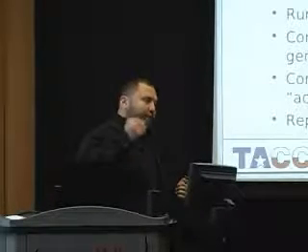So you start off with lots and lots of ensembles, lots and lots of models for the reservoir. And you run them, and you hit a time where you actually have production data. Usually for vanilla type reservoirs, that's every week. You have pressure readings from the actual wellhead, let's say. You compare what the models say you should have in terms of pressures, flow rates, bottom hole pressures, compositions, etc., with what you actually get from the field. Based on that, you modify your models so that they adhere more closely to the actual production. And you repeat this for as long as you have historical data of the actual reservoir.